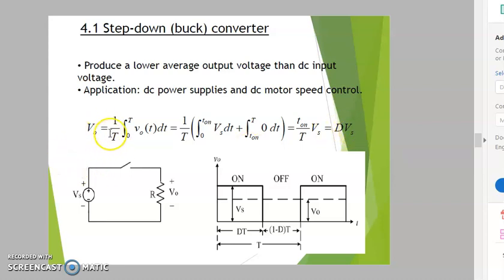So this is the V out average, and it depends on how much the duty cycle varies. If we adjust to a certain amount of duty cycle, we shall see V out, the dotted line. If we squeeze the duty cycle narrower, V out will reduce accordingly. The maximum is 100% duty cycle, the minimum is 0.